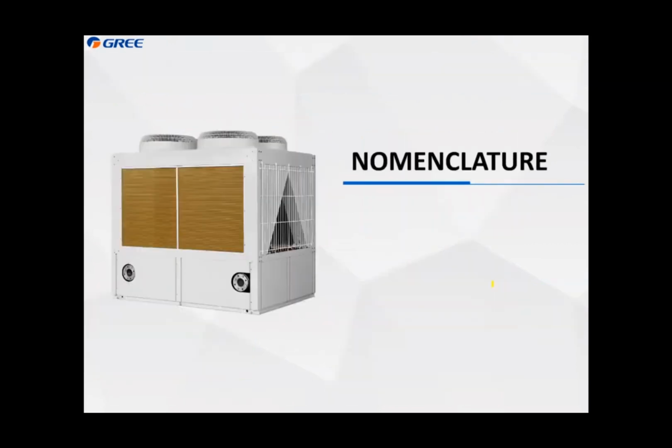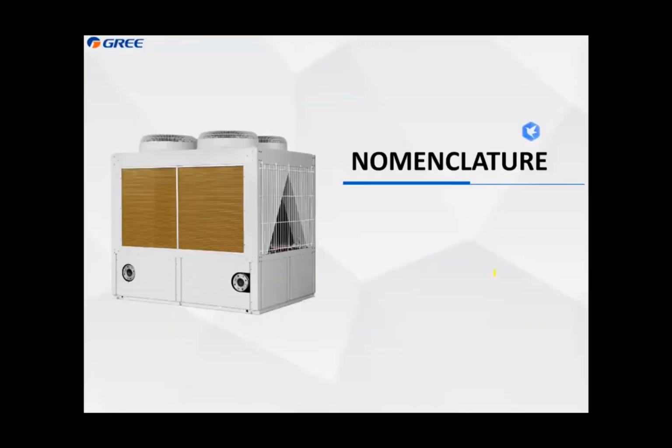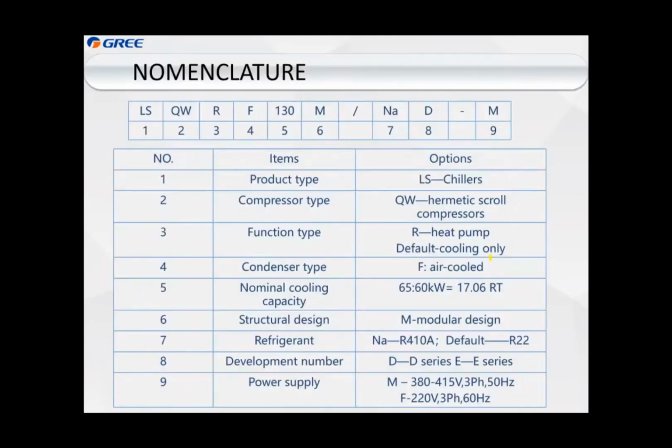And then next we see the nomenclature. From this table we see that LS is chillers, QW is hermetic screw compressor, and function tab. Condenser tab: F is air cooled. Let's mainly pay attention to this letter M, modular design, and NA means this is R134A. The default is R22.